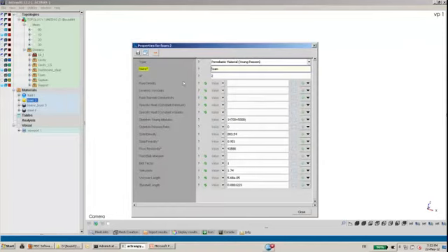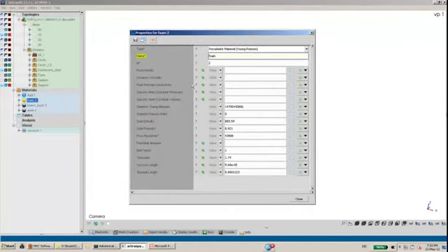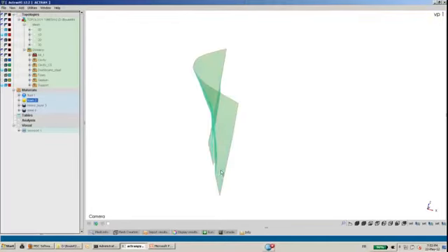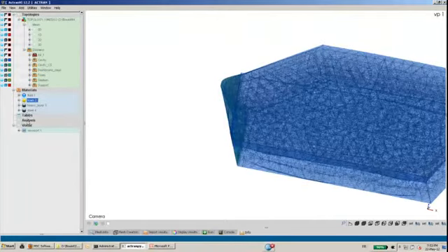Let's double click here on the foam to see all the properties required for a porous material. You can see that part of the fields here are blank, meaning that default values will be used. So this field can be left blank, or to access the default values, I can click here, as I mentioned earlier. So now I have my materials. The next step is to create the analysis. For that, I go here on the left-hand side, the analysis node.